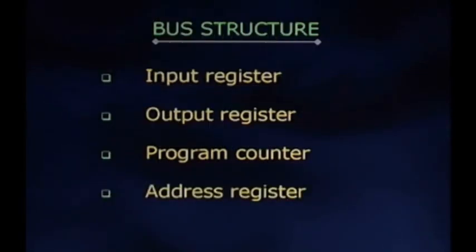The next register is the address register. The address register, or memory address register, is used to store the address of the memory whose contents have to be read or written under the instructions of read or write signals. The memory address register will also have the same facilities as the program counter.